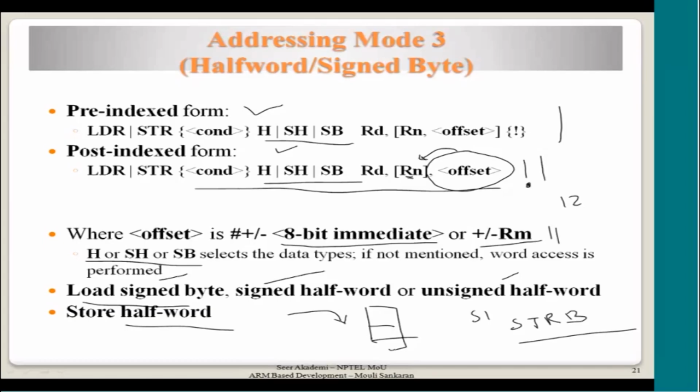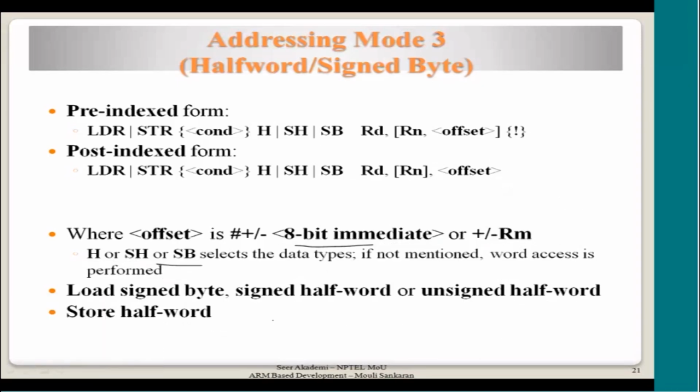So STR you could have used it. So this instruction, that's why it doesn't support storing other bytes. Only half word is not supported because the STR instruction doesn't support half word store. It only supports byte, or if you don't mention a byte, it is only a word. So these are the different things supported in this particular mode 3 instruction.